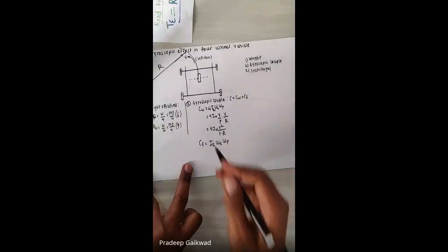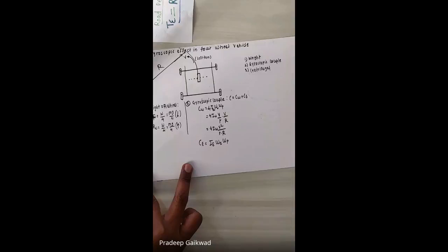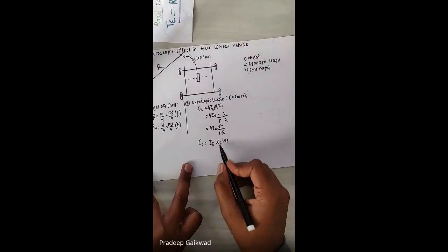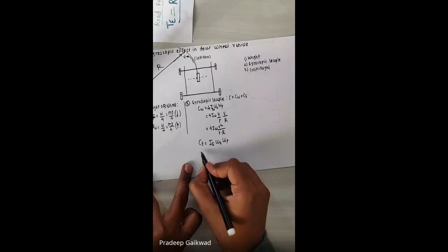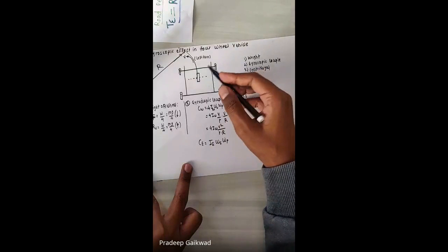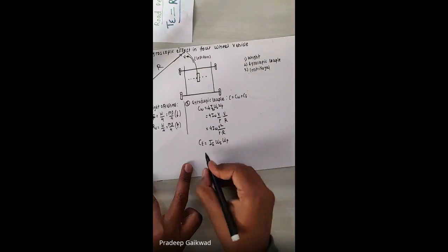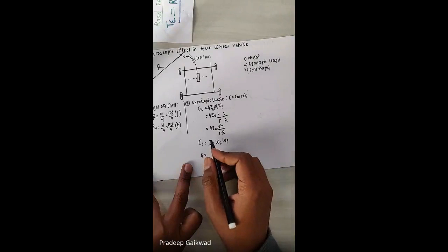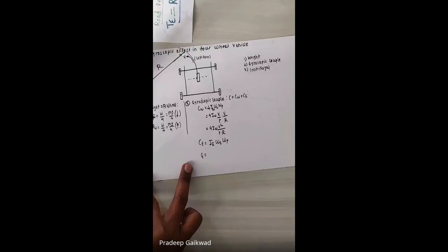So omega P is the same in both cases, but omega E changes. So how can we write this in terms of the gear ratio? As the speed is transferred from the engine to the wheels, I can write gear ratio G is equal to omega E upon omega W.